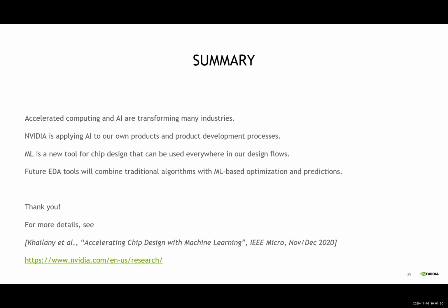Sure. So the problem with a hypergraph is that a net connects multiple nodes, right? One of the problems with chip design is that usually these nets sometimes have high fan-out. The distribution of the net nodes and the cell nodes or device nodes are really different. So that's why in the ParaGraph work we propose to treat the nets as a different type of node from the device. So it's kind of like a heterogeneous graph. You have different types of nodes: net nodes, cell nodes, and device nodes.